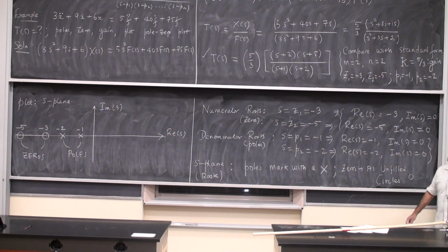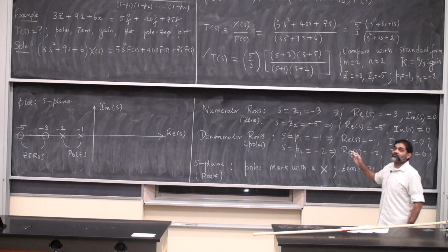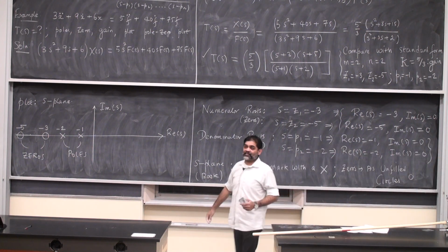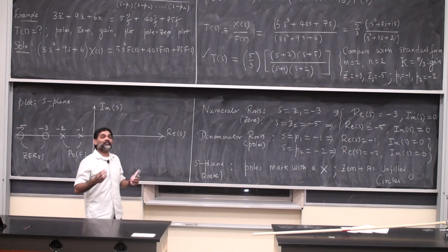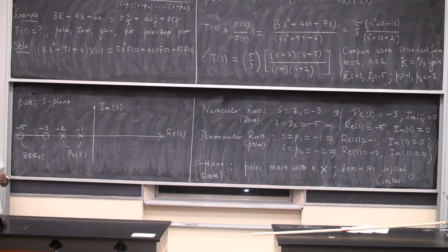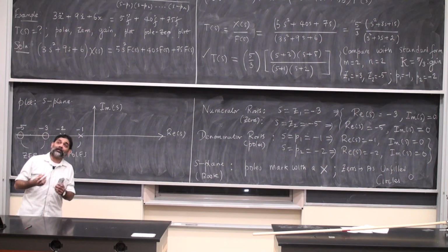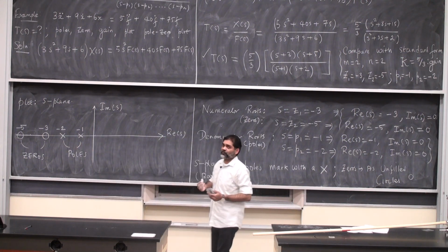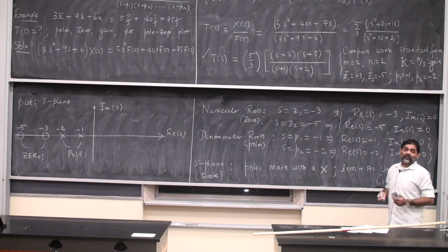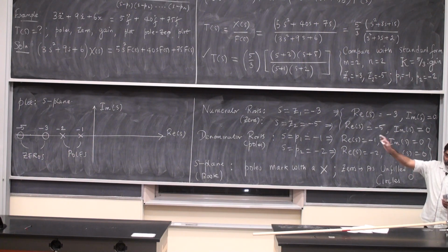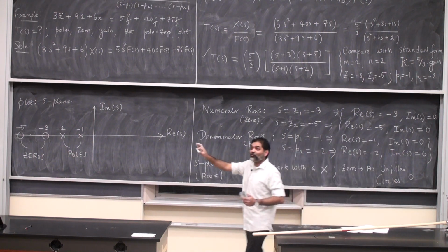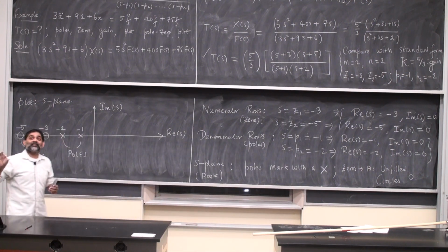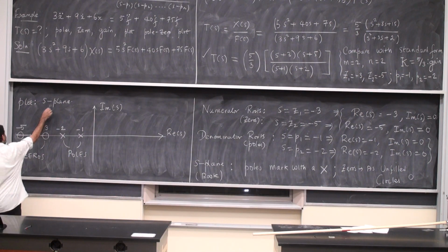And these types of systems, where you see that there are these zeros present, have what is called numerator dynamics. That is, there are some funky things happening in the numerator of the transfer function. You change the numerator, you change the coefficients. Perhaps if you're studying a step response, the magnitude of the peak could reduce, the peak time could be shifted, and so on. Is the system stable or unstable? All the poles are on the left half of the S-plane, so the system is stable.